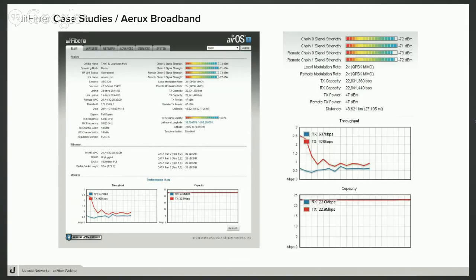A few things that we've really appreciated about the AirFiber product line. Initially when it rolled out, I think it was the AirFiber 24s, we had set up a backhaul link for one of our towers. We're getting about 640 megs each way, so about 1.2 gigabits of aggregate traffic. We were thrilled. Who doesn't like a good solid link like that? I want to say it was 2 months later, and Chuck might correct me. They came out with new firmware, and they were able to fit in more data rate modules into the radios. Essentially what that equated to was another 100 megs. So now that same link, just with a firmware upgrade, is now running about 740 megs in each direction, or about 1.5 gigs. With any other company, you'd end up having to pay for a license unlock feature, or you would have to pay for the new firmware upgrades.